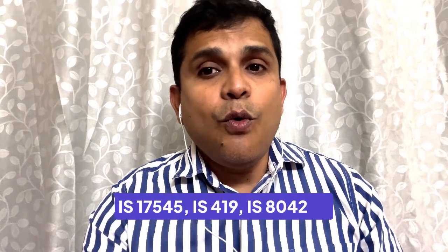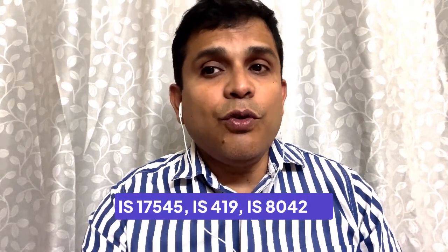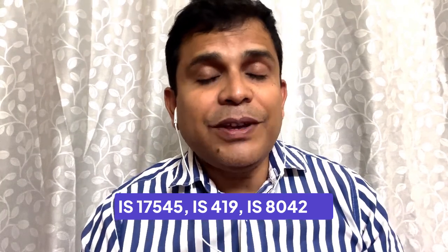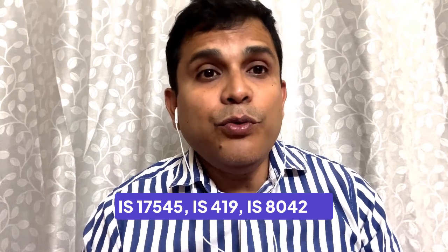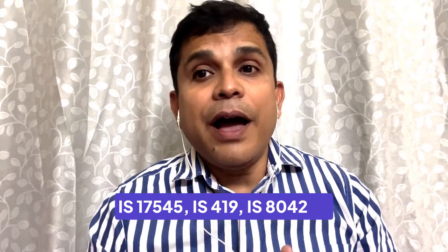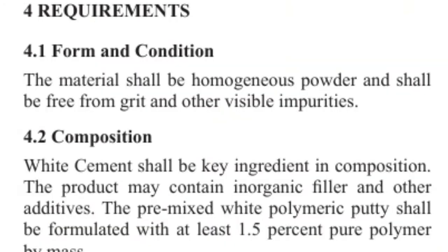Now, what are the IS code references? The IS code references are IS 17545, IS 419 and IS 8042. We already know the different types and the IS codes. Now we have to know the requirements, and that requirement is given in IS 17545 in clause 4. What does clause 4 say? Form and condition. In 4.1, the material shall be homogeneous powder and shall be free from grit and other visible impurities. That means there will be no impurities.